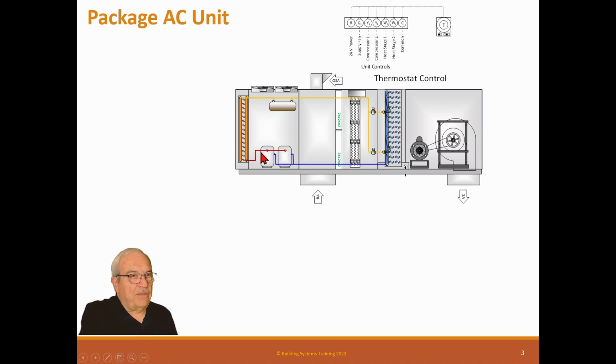And they have check valves here, so now we have gas pressure on the backside of the solenoid valve. So when the system says I need cooling, it opens that solenoid valve, and we immediately have liquid refrigerant to the expansion device to be able to start the cooling immediately.